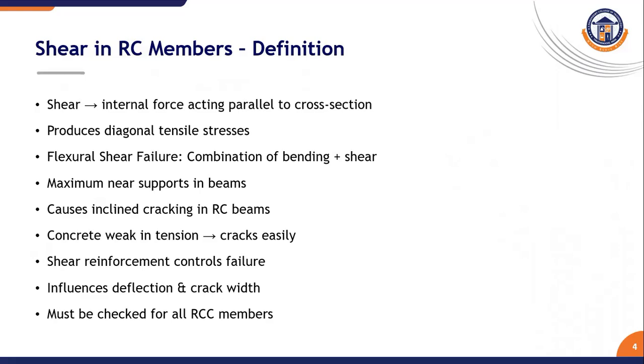Shear in RC members: definition. Shear is an internal force acting parallel to a section, producing diagonal tensile stresses. It is maximum near supports in beams and causes inclined cracking. Since concrete is weak in tension, reinforcement is required to control it. Shear must be checked in all RCC members because failure is sudden and brittle if not properly reinforced.